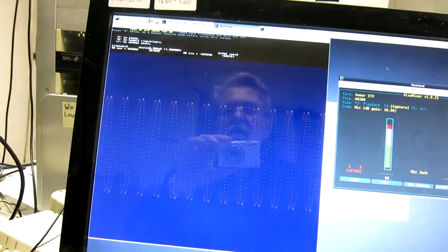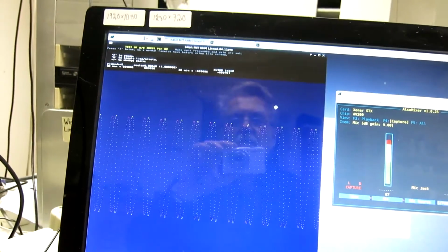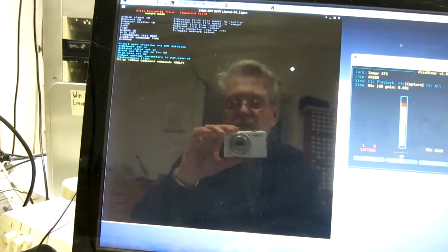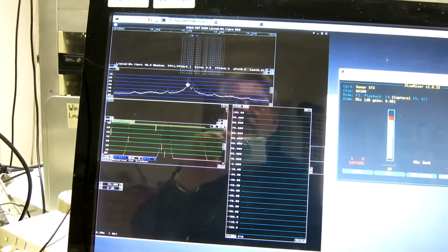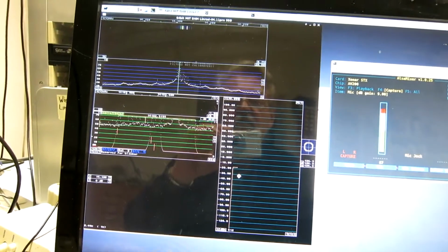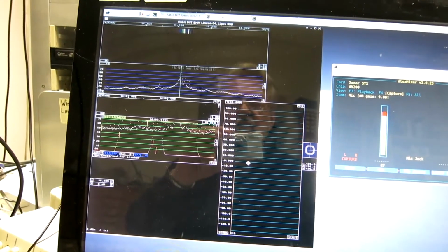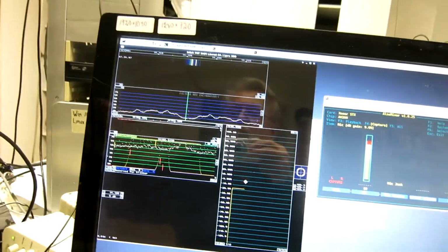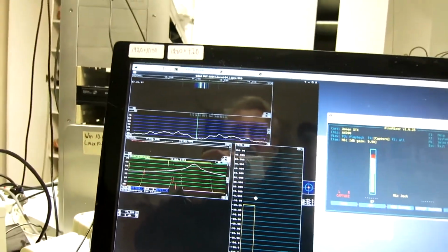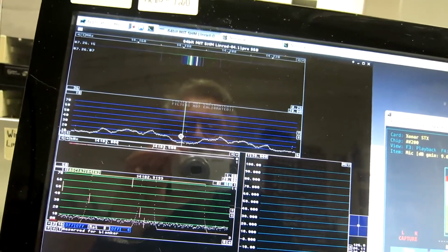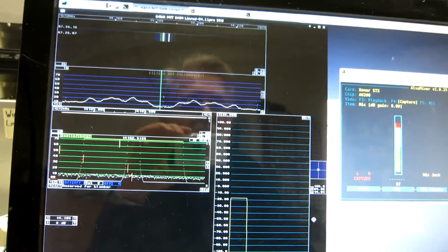And if I go back here, X, and look at the signal here, the level is still minus 18 dBm. And if I switch off the signal generator, now as you can see, at very low frequency, the noise floor is a little bit better.